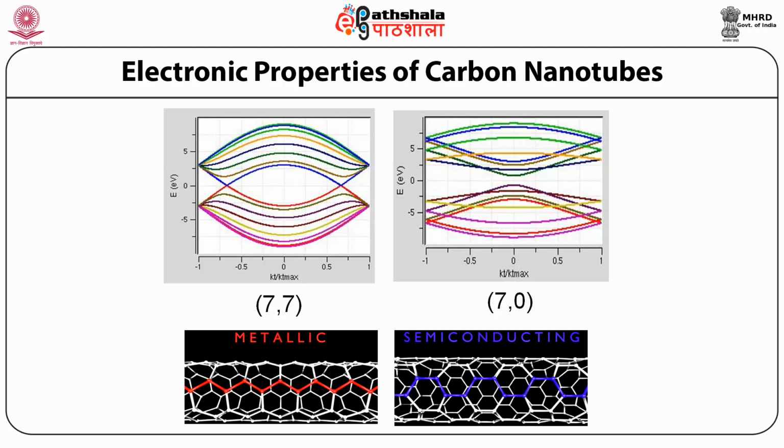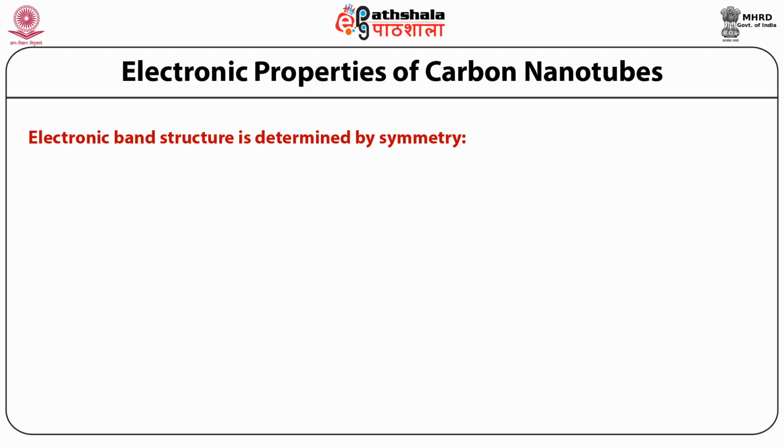Some types of armchair structure CNT appear to conduct better than other metallic CNT. Furthermore, interwall interaction in MWCNTs has been found to redistribute the current over individual tubes non-uniformly. However, there is no change in current across different parts of a metallic single-wall CNT. The behavior of a rope of semiconducting SWNT is different in that the transport current changes abruptly at various positions on the CNT.